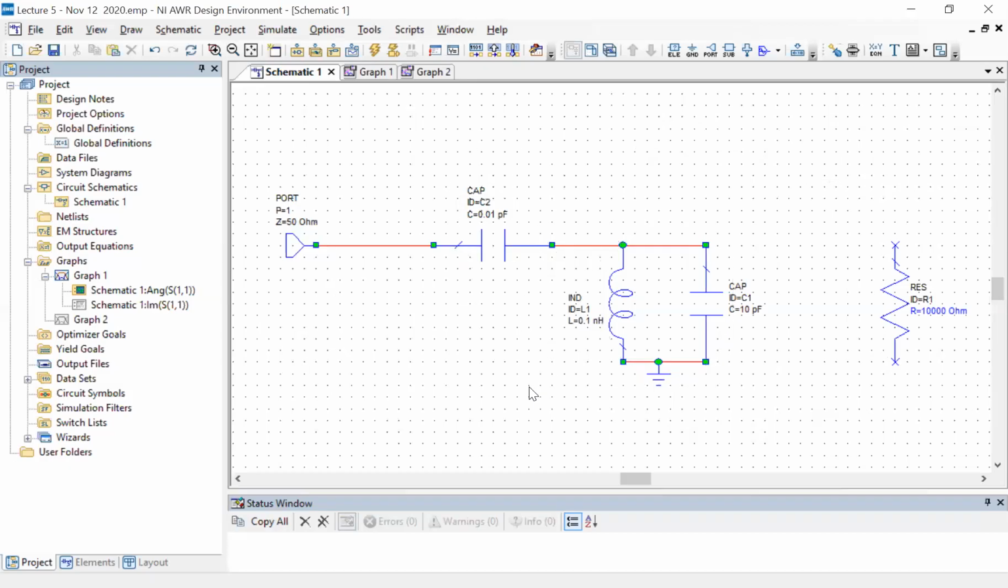So this is now a way. And remember that this almost completely controls the overall dissipation, because 50 ohms is fixed. We already said that L's and C's cannot change that much. Of course, if L's and C's change, it will change the quality factor as we had discussed before. But it's now a lot easier to control, because you need a small capacitor to reduce the dissipation, which is usually the direction one tries to go.